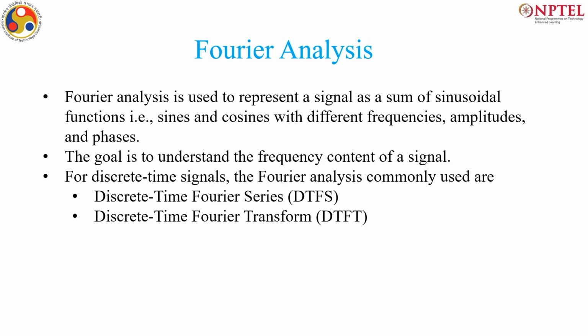Fourier analysis, as I introduced in the previous video, is used to represent the signal as a sum of sinusoids, like sines and cosines, with different frequencies, amplitudes and phases. The goal is to understand the frequency content of the signal. For discrete time signals, because here we are mainly focusing on discrete time signals, there are two common types of Fourier analysis: the discrete time Fourier series, or DTFS, and the discrete time Fourier transform, or DTFT.